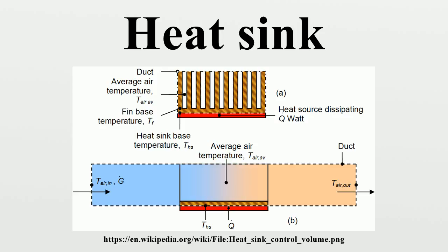Surface color. The heat transfer from the heat sink occurs by convection of the surrounding air, conduction through the air, and radiation. Heat transfer by radiation is a function of both the heat sink temperature and the temperature of the surroundings that the heat sink is optically coupled with. When both of these temperatures are on the order of 0 degrees Celsius to 100 degrees Celsius, the contribution of radiation compared to convection is generally small, and this factor is often neglected.